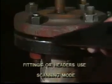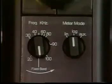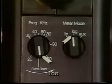To locate a leak in fittings or headers, use the scanning mode. With the ultraprobe scanning module in the fixed band position and set at log, scan a general obvious area. Adjust the sensitivity on the ultraprobe to focus in on the loudest point, moving from gross to fine sounds, or closer and closer to the leak site.